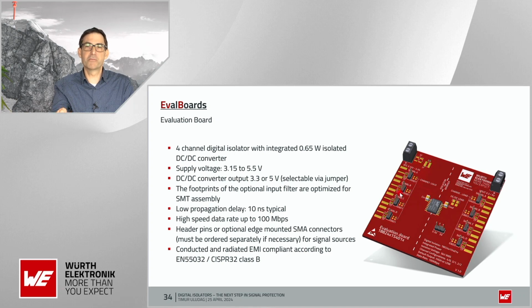You have the pin headers so that you can feed in your signals. This board is valid up to 100 megabits. If you don't want to use the header pins, you have some space so that you can also go for edge-mounted SMA connectors. We have the screw terminals, and also the pin headers, or at the output the edge-mounted SMA connectors, so that you can get the signals out.